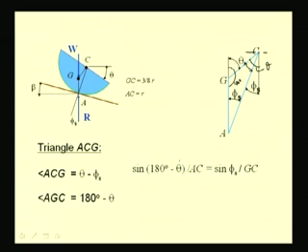So, we take this angle opposite to this edge AC, that is sine of 180 minus theta divided by AC, equal to sine of this angle phi s divided by this length GC. Since we know these dimensions GC and also this dimension AC and this angle phi s, from this we can determine this theta, and the same has been determined as 50 degrees.